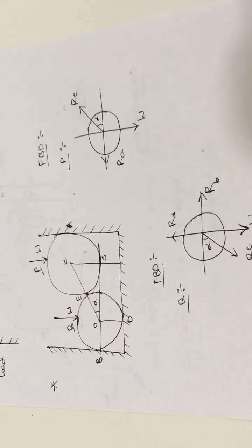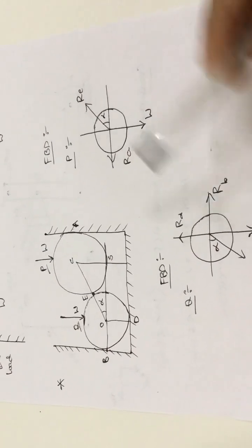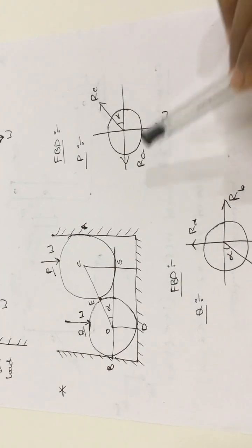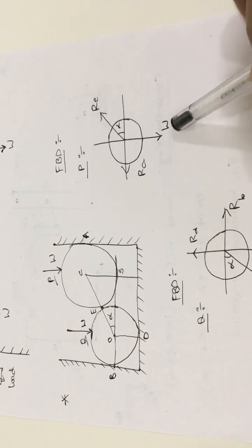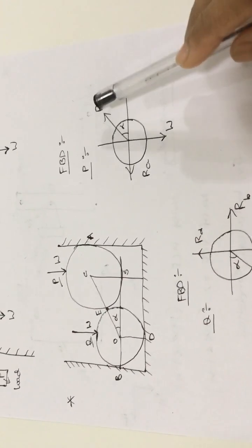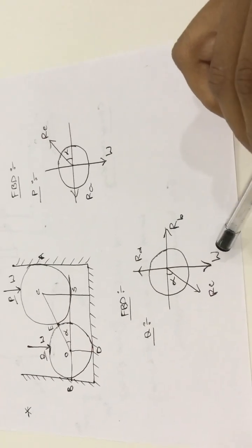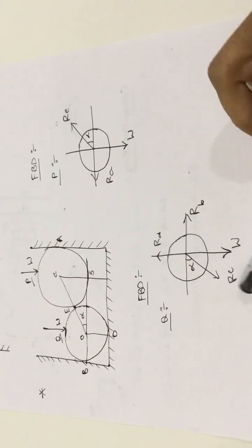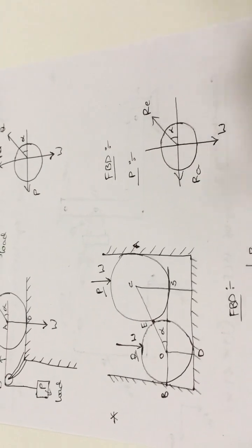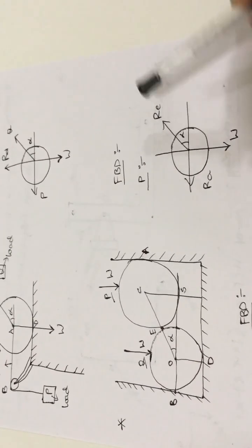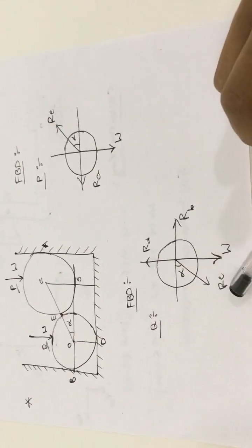And one more thing, for such a type of the problems generally here two balls are there. P is the first ball and Q is the second ball. Here for the P ball three forces are there. Out of the three forces W value, magnitude value will be given in the question. So two unknown values are there. Here out of the four forces, one value is the known value. So three unknown values are there. So first of all we should calculate the problem according to the less unknown quantities. For the P ball two unknown quantities are there. For the Q ball three unknown quantities are there.